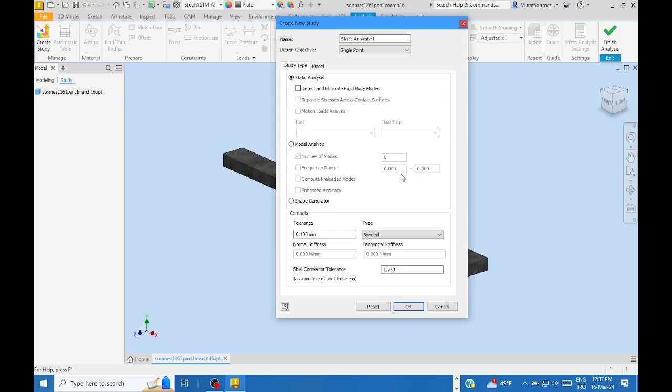If you know the resonance frequencies of the structure, for avoiding purposes, then accordingly you can select the speed of rotation. There are two alternative electrical motors. One of them is 2000 RPM, the other one 3000. Which one is to be selected?